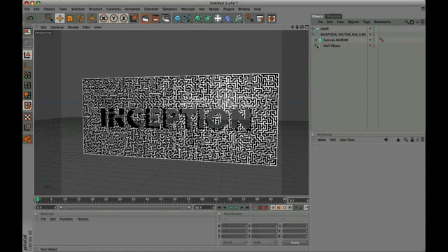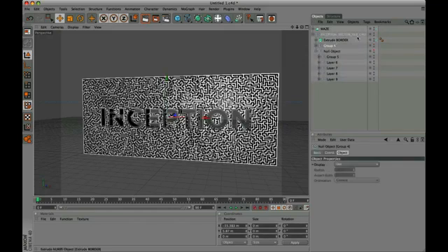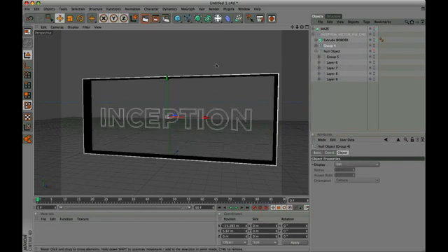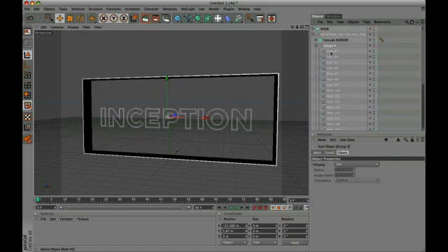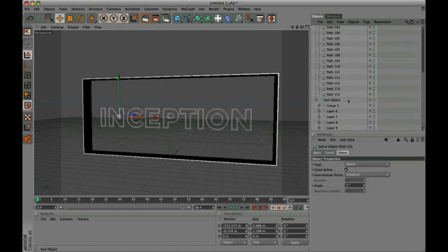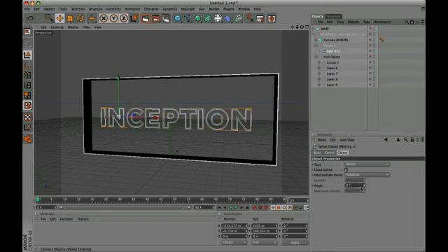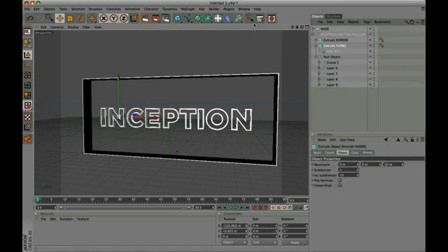Proceed with the group 4, drag out and disable the maze visibility. Select all the splines and connect all. Drag it out and delete group 4. We apply the extrusion with value 150. Rename, extrude logo outline, and disable visibility.